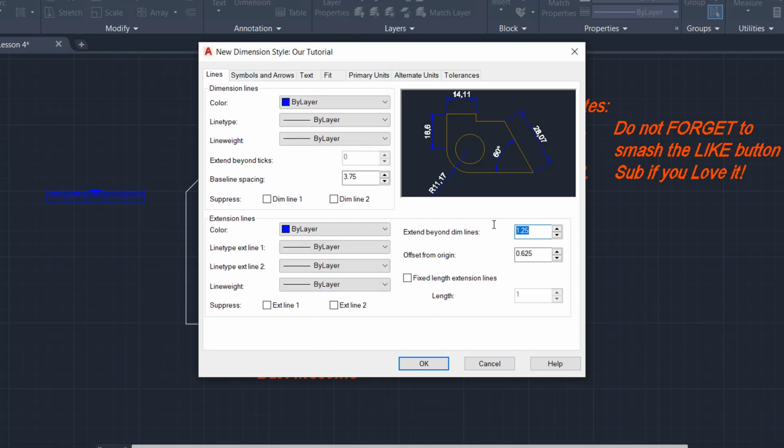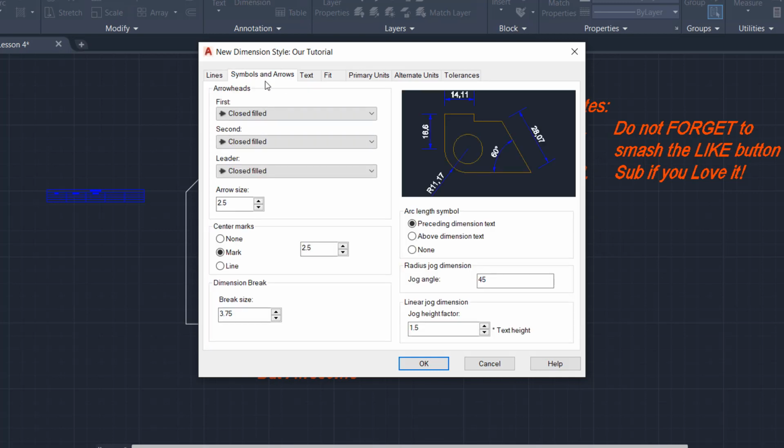Extend beyond dim lines will extend above the dimension lines here. Let's make it 4 and see. I hope you can see the elongation right here. If not, try it out yourselves and you will see. Offset from the origin is the gap between measured object and extension lines like here. Let's make it 4 also. You can see that the gap got bigger. That's our lines setup. Now let's see symbols and arrows.